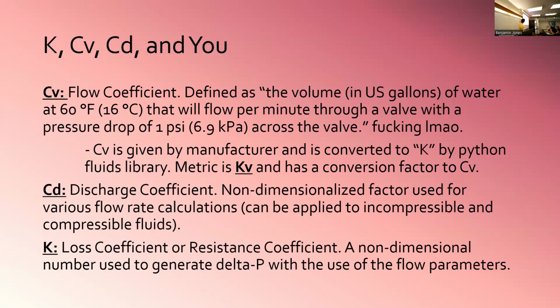CD is discharge coefficient. Discharge coefficient is non-dimensional once again, very similar to CV, but it's used in regards to how we characterize fittings and systems. So CD can apply to a lot of things. It can apply to a fitting in a tube system. Typically, it applies to just a fitting system. And you can find CD information online. So if you have a geometry that you know, you can look up research papers or textbooks, and they will have CD values for those geometries.